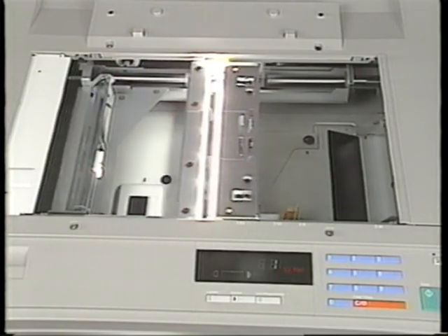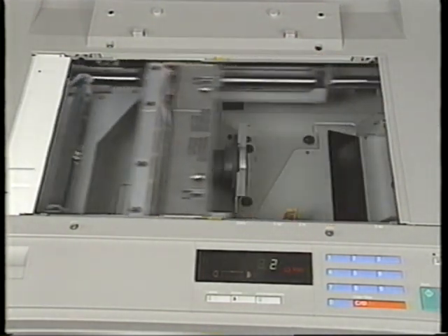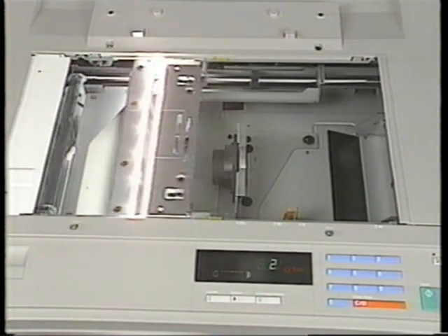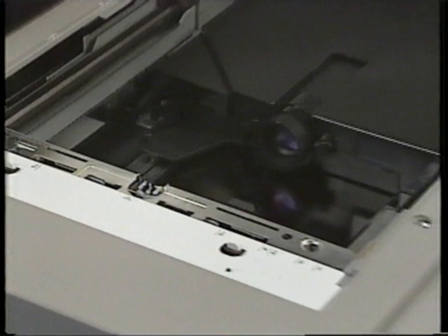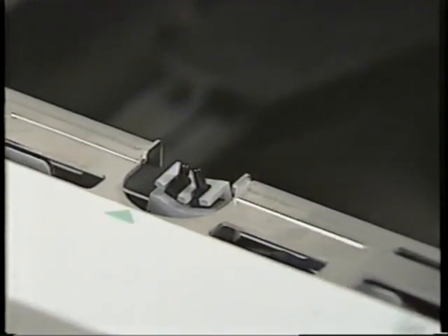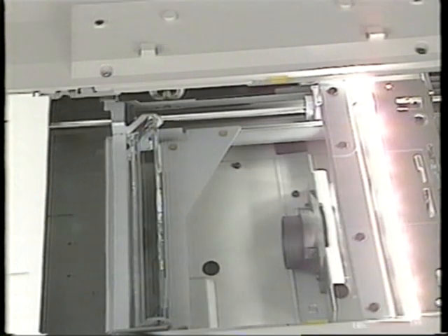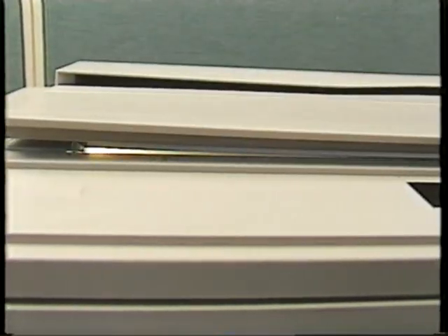Before exposing the original, the copier performs a pre-scan check. In this operation, a fiber optic cable on the first scanner passes a reflected light reading from the original to a photosensor. Low reflectance from the original indicates a darker than normal surface. This usually means colored paper, which might cause a gray background on copies. To avoid this problem, the control system adjusts the exposure lamp voltage.